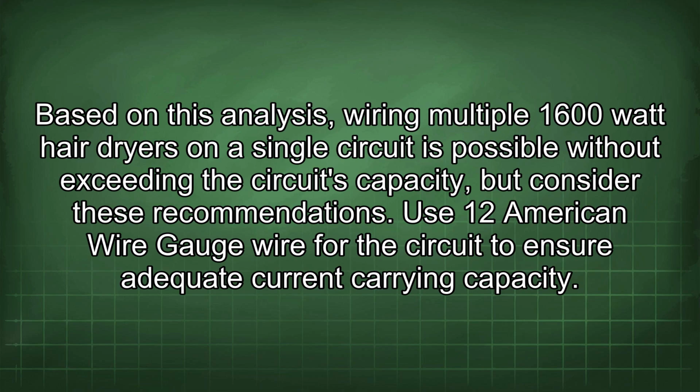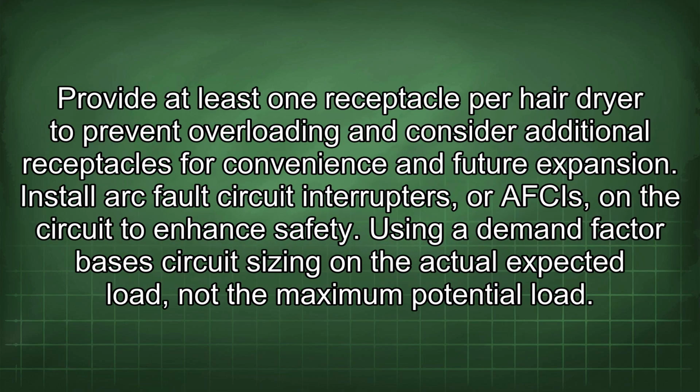but consider these recommendations. Use 12 American wire gauge wire for the circuit to ensure adequate current carrying capacity. Provide at least one receptacle per hairdryer to prevent overloading and consider additional receptacles for convenience and future expansion. Install arc fault circuit interrupters, AFCIs, on the circuit to enhance safety.